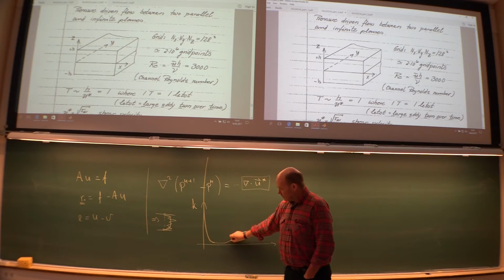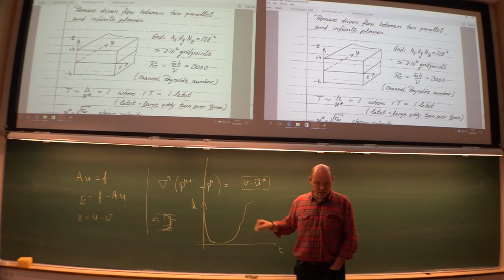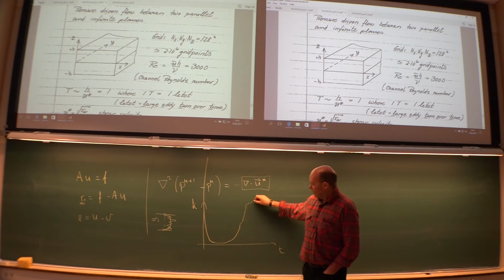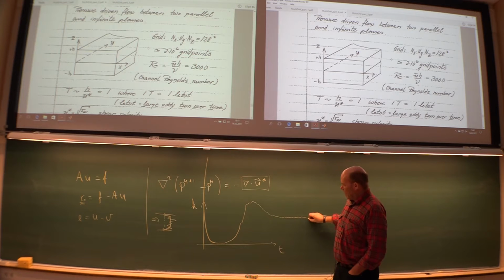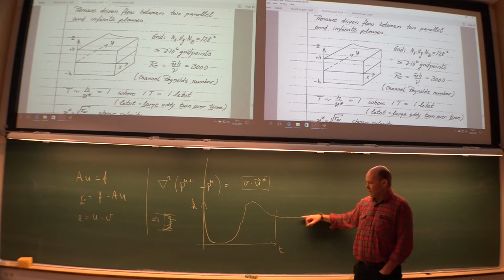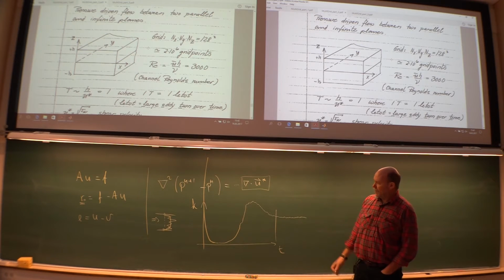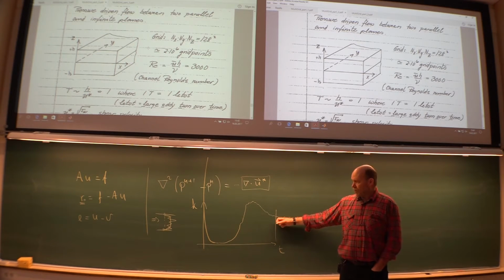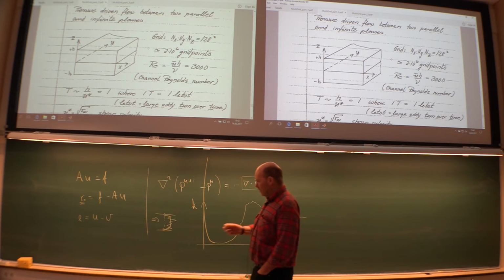But finally it started to build up the turbulent kinetic energy. Then I was worried, will it explode? But finally, after some time, it leveled off. And from here on, I could say, now I have a steady situation. It's still fully turbulent, violent behavior, but from here on I could start calculating data. I could start making statistics.